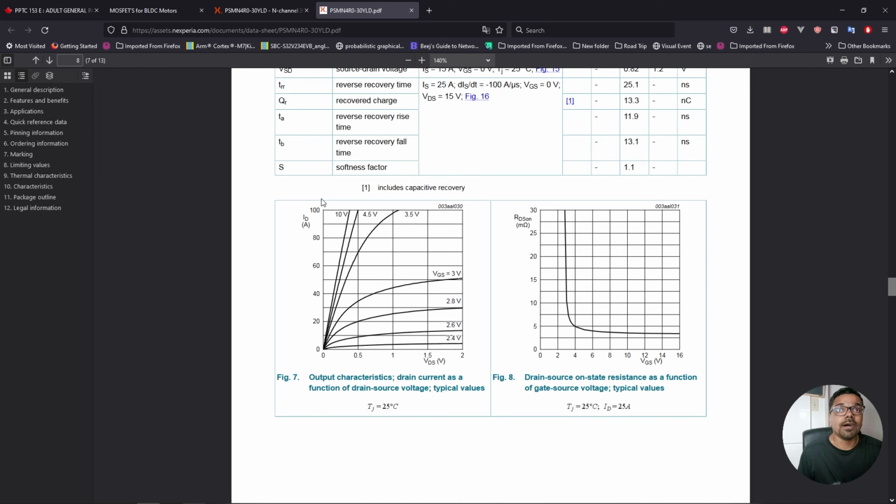As I mentioned, there are the Q parameters. These are the dynamic characteristics, this is the capacitance. So gate to source charge, total gate charge, input capacitance, output capacitance. We did speak about the reverse transfer capacitance, the Crss. And then we have the turn on delay time, rise time, and we'll make more sense of all of this. What is the plateau voltage? This has got to do with the Miller effect.